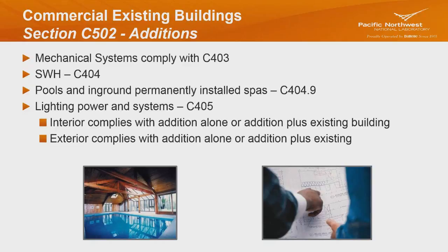Lighting power and system. So with lighting, if you have an addition, well, it's fair game. Interior lighting needs to comply. And you can comply with the addition by itself or the addition and the rest of the building, the existing building. And keep in mind, exterior also needs to comply. So if you have exterior lighting on that addition that's new, then that needs to comply as well.